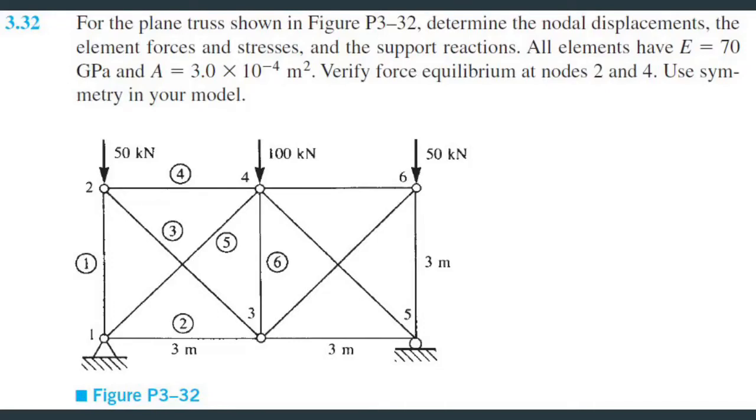Alright guys, this problem is crazy, like legit crazy. So let's go ahead and get started, right? They give you EALs, you gotta find some lengths, but that's not a problem. We gotta find stress, forces, nodal displacements, and verify force equilibrium at two nodes, and we have to use symmetry. So let's go ahead and get started.